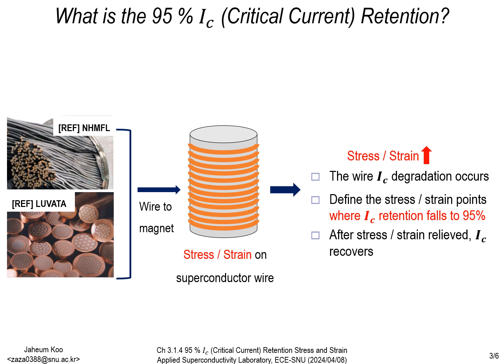During the winding process, the superconducting material undergoes stress and deformation. For example, around the central bending neutral axis, the inner surface of the wire experiences compressive stress, while the outer surface undergoes tensile stress. These stresses and deformations can damage the critical current capacity of the superconducting wire.